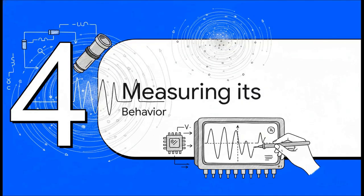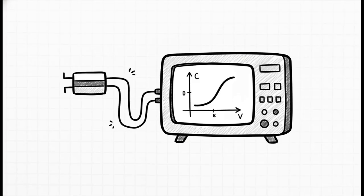So we have these three cool electrical states. But how do engineers actually see what's going on? I mean, how do you measure something that's happening on such a tiny scale to make sure it's working right? Well, we can't look at it directly, but we can measure its electrical fingerprint. It's called its capacitance voltage, or CV characteristic. Basically, by tracking how its ability to store a charge, that's its capacitance, changes as we tweak the voltage, we can map out exactly which state the device is in.